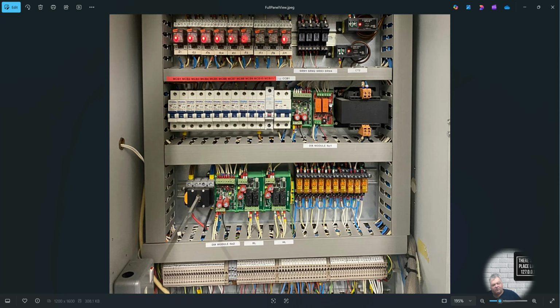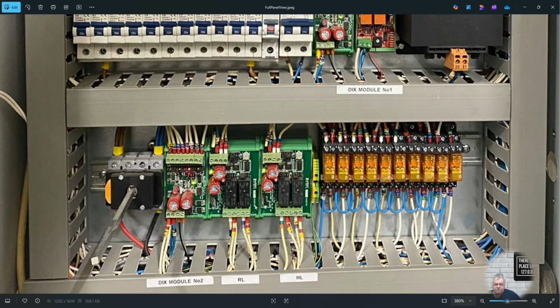So you give it 5 volts to switch the pumps on, you give it 10 volts it switches the boiler on. This is slightly different, the raise and the lower. This is where 7 volts is not raising the valve, 4 volts is lowering, 10 volts is raising the valve. But we can look at that later in the logic, so we've got to write logic for them.